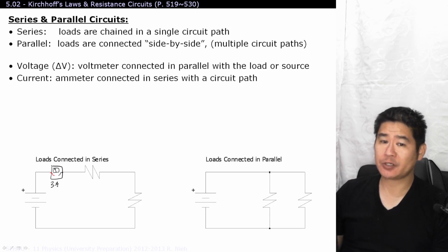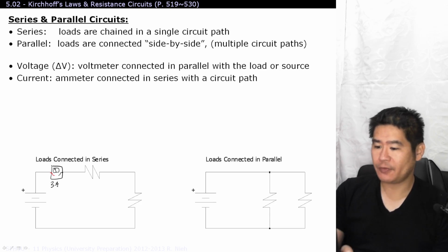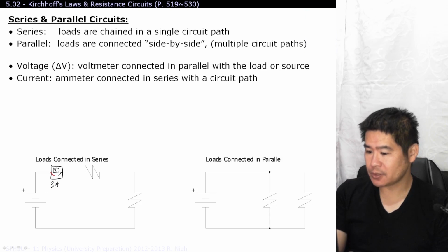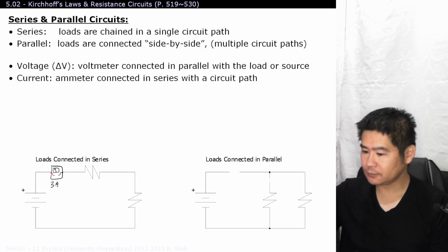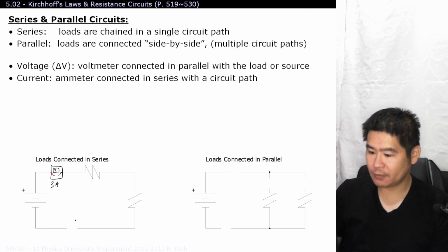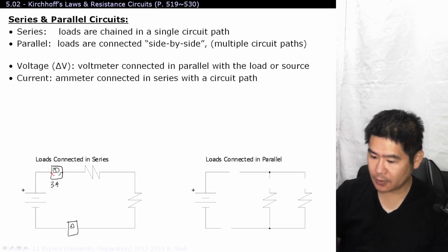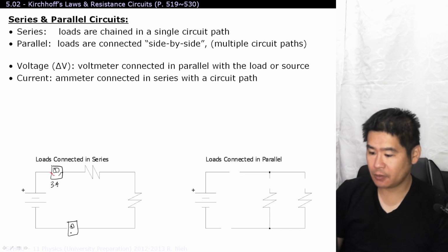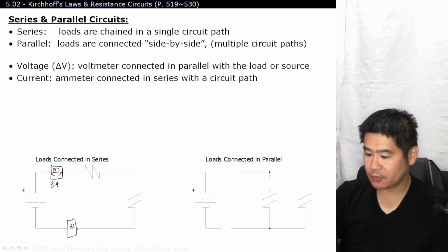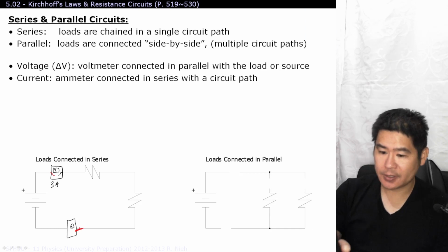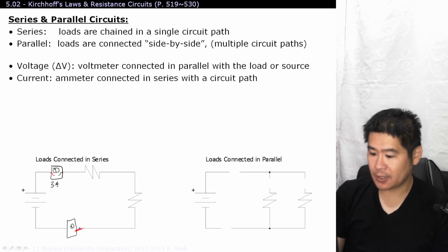It's a lot of electrons that are flowing per given second. Well, we can't just have electrons disappear in a circuit. So if I was to break open another opening somewhere else in the circuit, let's say right down here, and then I reconnect it together with an ammeter, again, the side, oh, wrong way. The side closest to the positive, you'll want to hook up the red to it, and the side closest to negative, you'll hook up right over here.